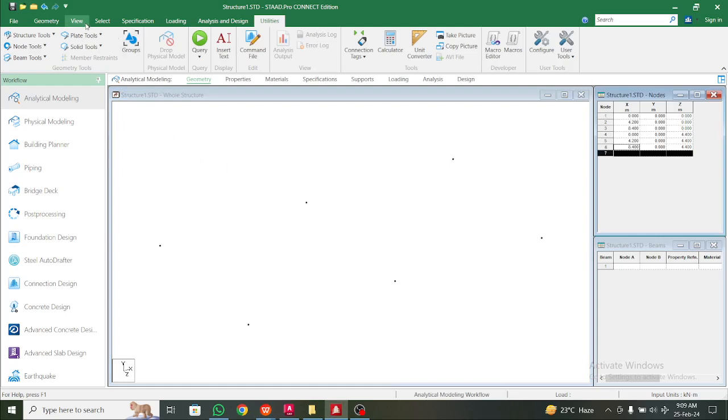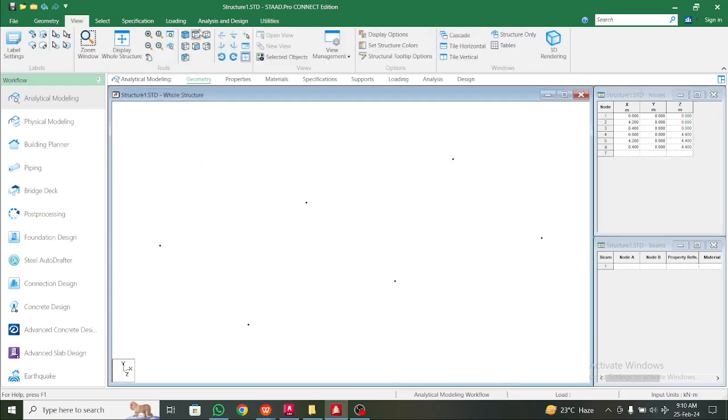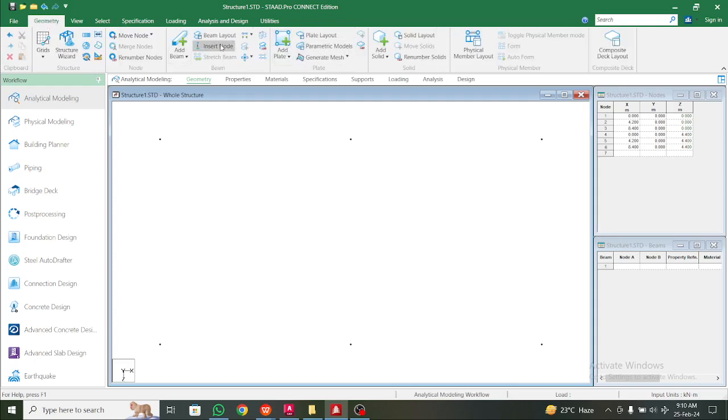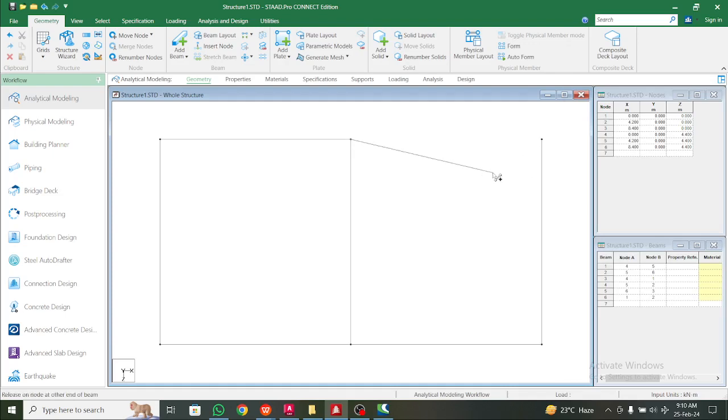Once the nodes are there, we go to the view and go to the top view, and then we can join it using the geometry option and add beams option. We join this nicely, left click and left click, and then join the vertical elements. Usually for complicated models also you go with the same order, left to right horizontal, then the vertical. And if you mess up and this option comes, just click on no and then put it in the nodes here.